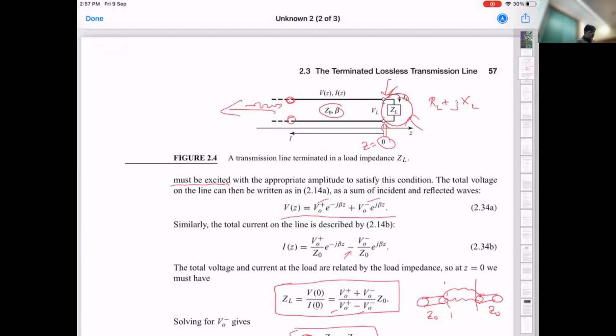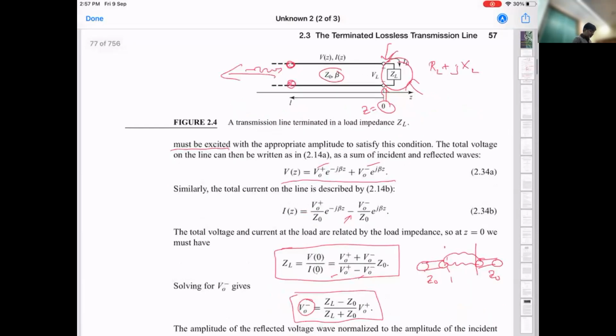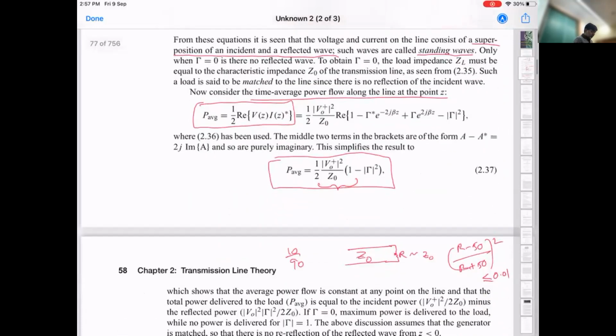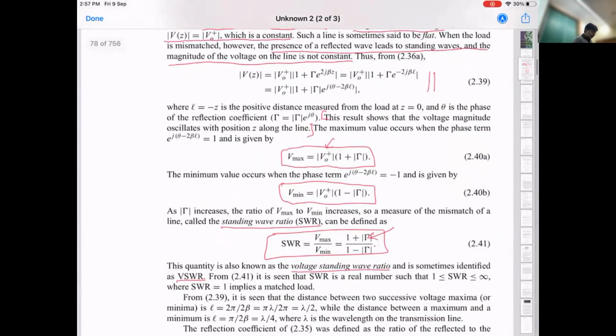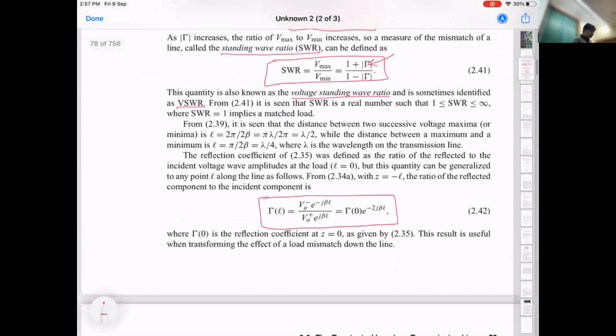So far we have been just talking about the situation where you have what is happening at the boundary of the transmission line and the load. But what we really want to know is, how do we think about the device when we look at it from some point which is further away from it? That can just be done by looking at the voltages and the currents away from that point. Using the wave equation, you can now extrapolate what those values will be.